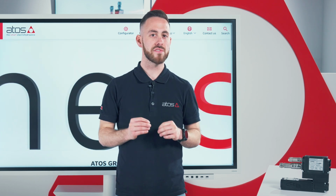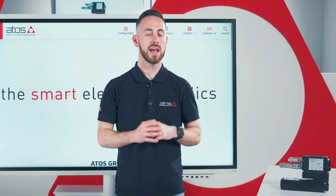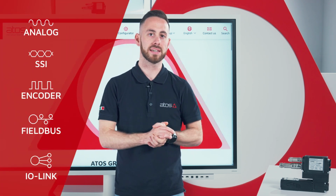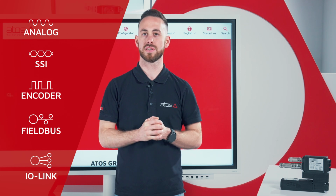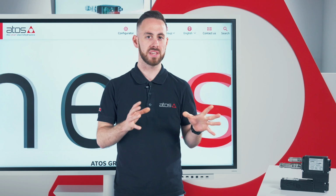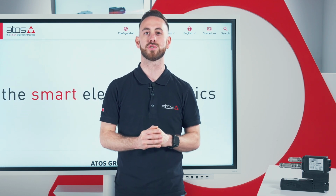However, there are several typologies of position transducer available on the market nowadays: analog, SSI, encoder, field bus, IO-link. But what are the differences and which one should be selected? Let's analyze together some of these categories and let's have a look at the main characteristic of a position transducer.